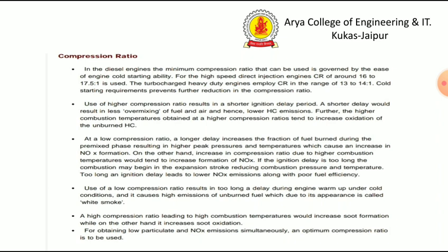Further, the higher combustion temperature obtained at a higher compression ratio tends to increase oxidation of the unburnt hydrocarbons. At a low compression ratio, a longer delay increases the fraction of fuel burnt during the premixed phase, resulting in high peak pressures and temperature, which causes an increase in NOx formation.